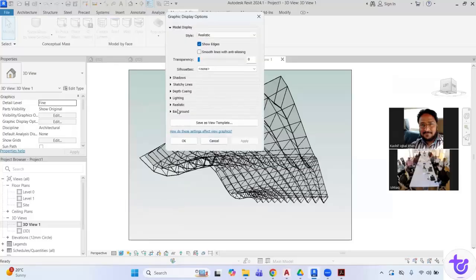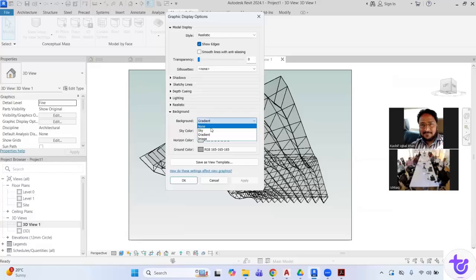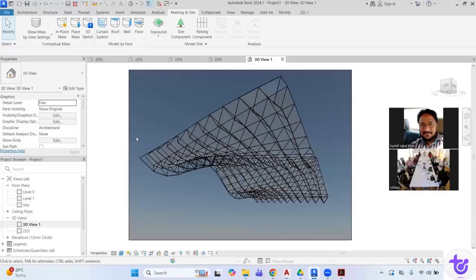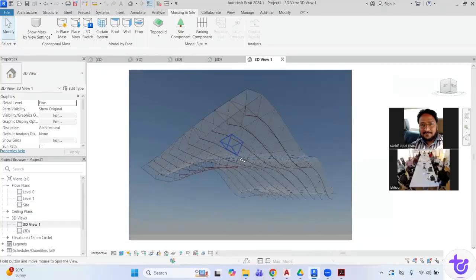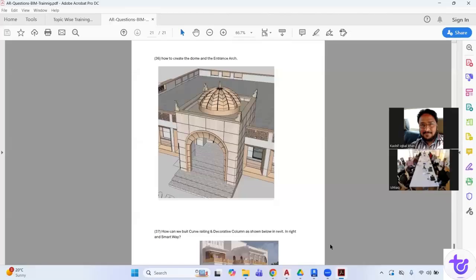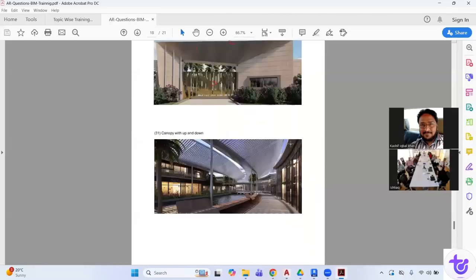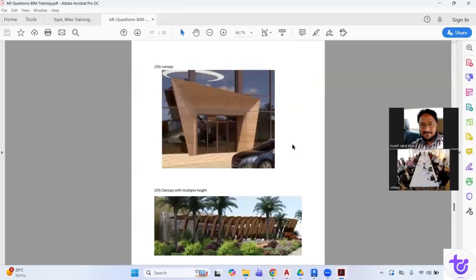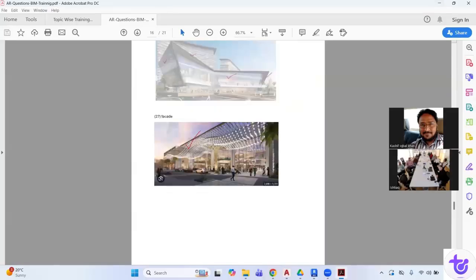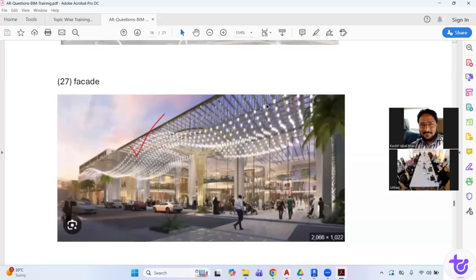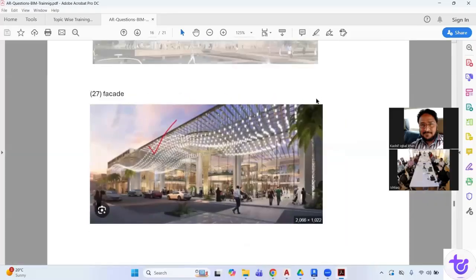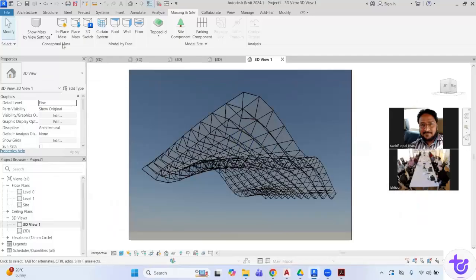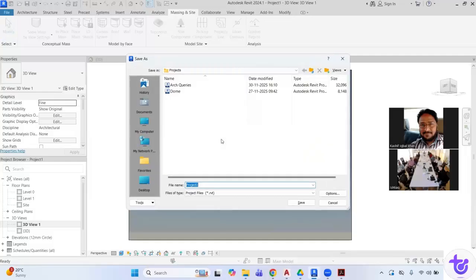So this is how this space frame can be done. Is that clear? As per your question, it was actually done. You can have any geometry in your section of the structure, and then accordingly, for example, if you have different details for the structure, you can create that adaptive family and then replicate it throughout the roof. Fine. So, should I close this? Yeah.